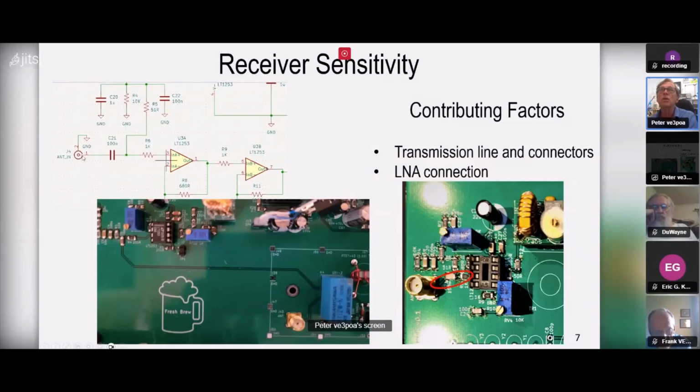Oh yeah, and you can see over here in the design, the input of the first stage of the LNA only has the resistor and the capacitor. On the Phoenix board, well, we kind of got away from that. There's the antenna input there, and then the receive follows this trace all the way over to the LNA over here. And that was due to, if we moved the relay and everything over to here, then we got a much longer transmit trace on the board. So I think it's still a debate to have with Dave over this, but anyway, that's the way it is now.